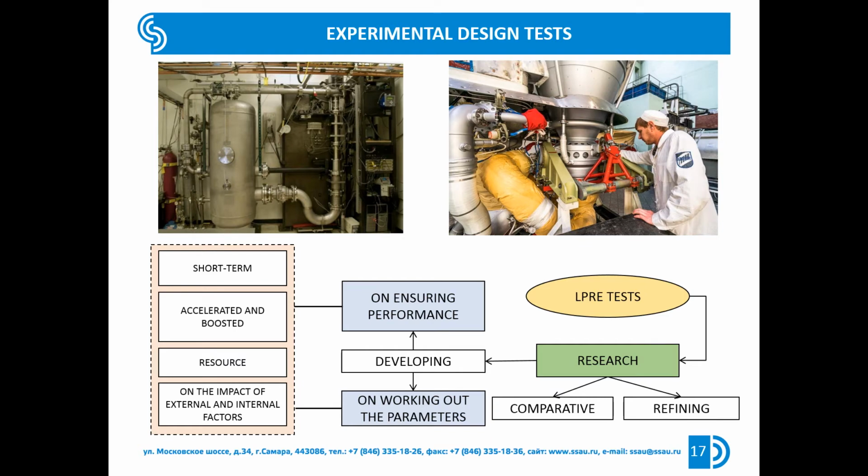Tests are performed up to a certain limit of change in factors. At the same time, tests are conducted for a period of time longer than that specified in the technical specification. The same liquid propellant rocket engine is repeatedly tested, thus increasing the operating time and the number of cycles for each of the liquid propellant rocket engines, and the operation modes are made heavier. The latter is achieved during accelerated boost tests by special tuning of the liquid propellant rocket engine to the limit values of main parameters by wide variation of operation modes with appropriate regulating elements.